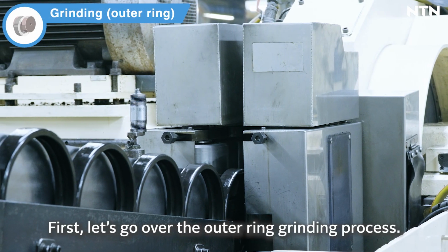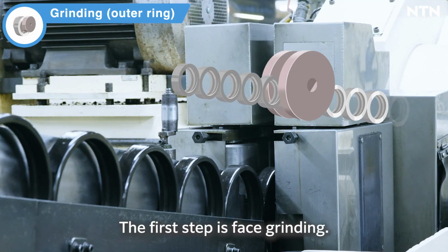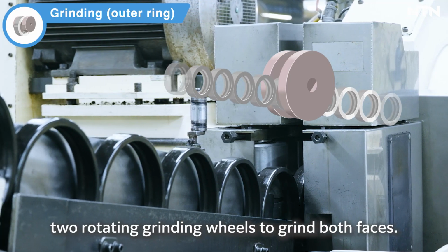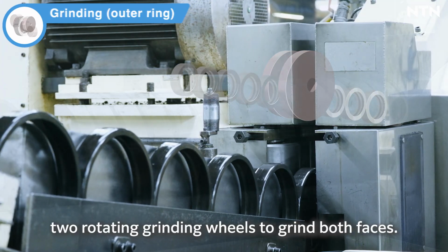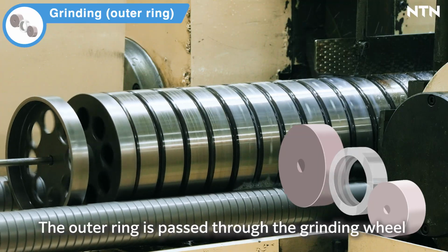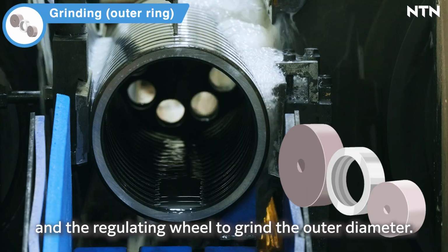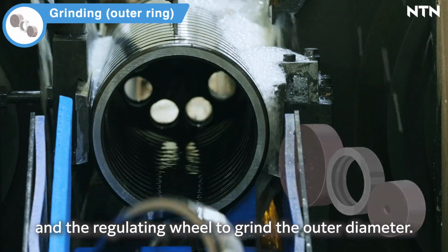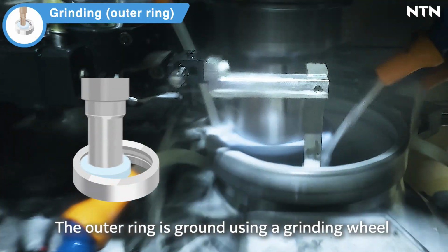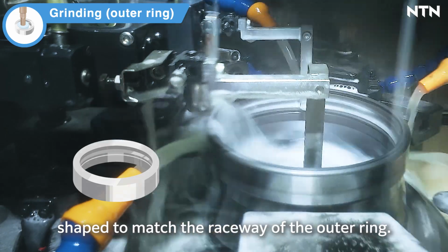First, let's go over the outer ring grinding process. The first step is face grinding. The outer ring is passed through 2 rotating grinding wheels to grind both faces. The next step is outer diameter grinding. The outer ring is passed through the grinding wheel and the regulating wheel to grind the outer diameter. Next is raceway grinding. The outer ring is ground using a grinding wheel shaped to match the raceway of the outer ring.